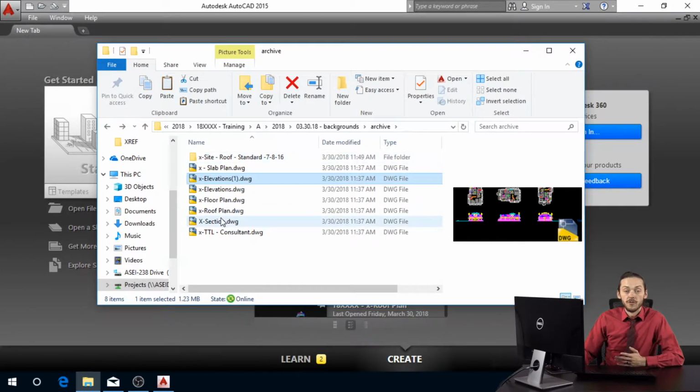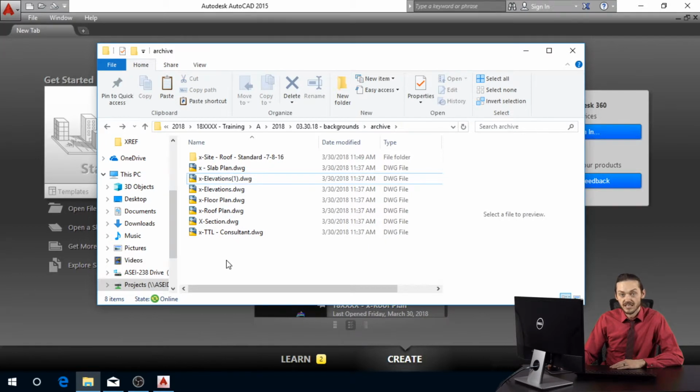So there is one other file type that will occasionally be sent over with these types of projects, which is the reflected ceiling plan, or RCP. In a project like this, more than likely what's happening is this floor plan that was given to us probably already also has the RCP in it, and the architect is just wanting us to freeze the elements that we don't need on those particular sheets. So on the sheets that show lighting components that require a reflected ceiling plan, we would freeze the floor elements, and vice versa. On the power plans or anything involving the floor plan, we would freeze the reflected ceiling plan elements.